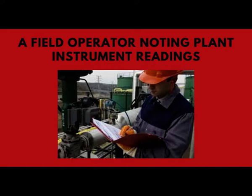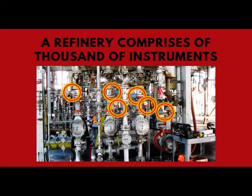So, in a petroleum refinery, so many process parameters need to be monitored, and as I said earlier, pressure, flow, level, temperature, and for all that different kinds of instruments will be deployed. And as a field operator, it is his job to note down all these readings at a set periodicity. For example, once in 2 hours or once an hour, he has to take a logbook and note down all these readings to ensure that the plant is not upset and the plant is running in steady state condition.